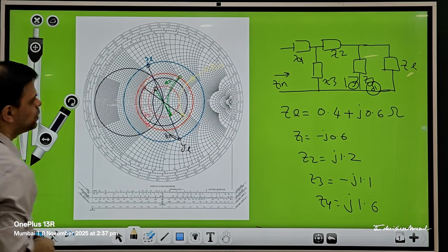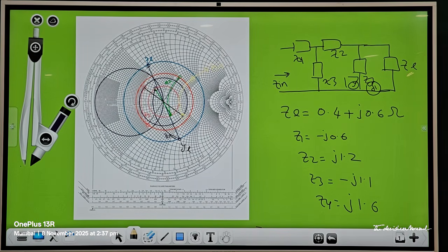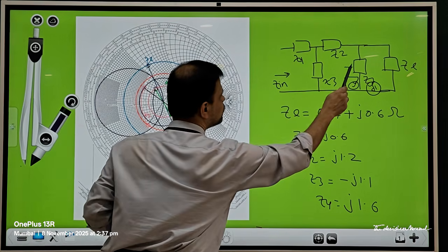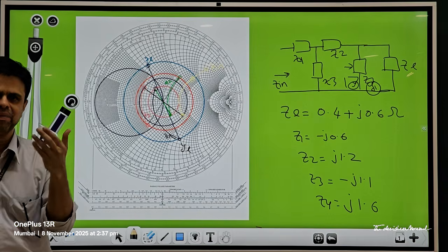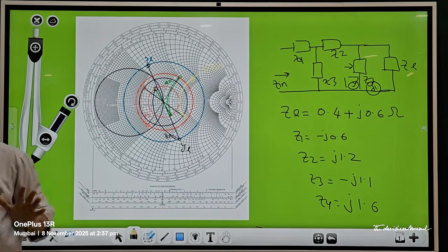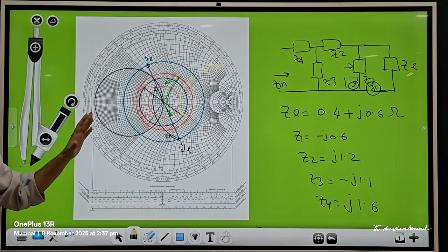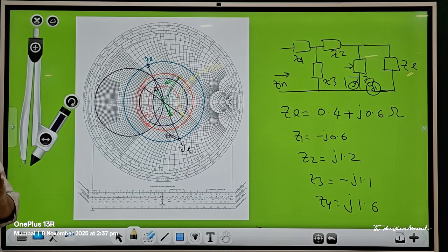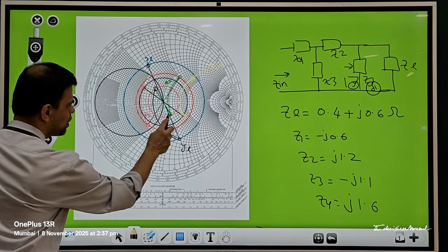You draw a constant gamma circle and take a diametrically opposite point over here. So you are now on Z domain, and you have calculated Z for this. Read that value. It will be 1 minus jx or 1 plus jx depending upon your actual values of the impedances. The corresponding graph representations I have shown, so that shows the appropriate proportion of addition of respective impedance or susceptance. Fine. So I have come over here.